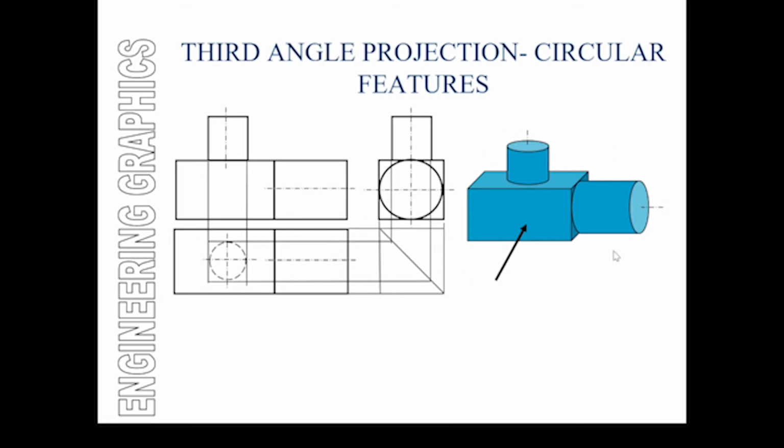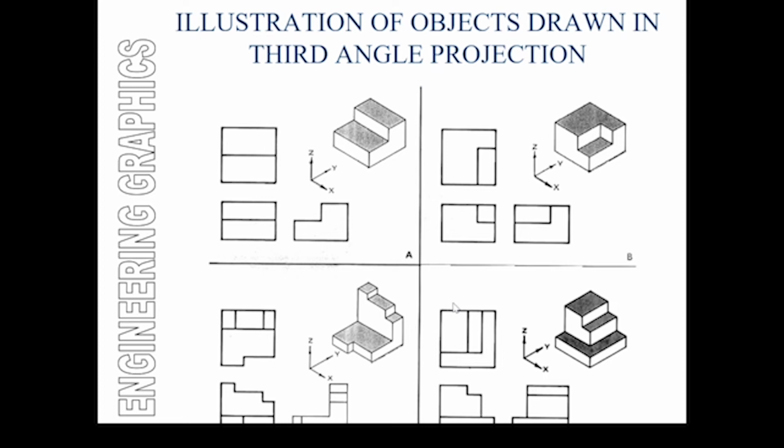You always have to imagine that you want to produce and provide information with probably only two views, and that should be enough for anybody to deduce the object they're looking at. And if you were to think about that and that view together, or maybe that and that view together, that's enough to know what this object is. Once you've seen it, it's difficult to unsee. However, if I hadn't seen that, I know there's a center line there, so that's a circular object. There's a center line there, that means it sits centrally, etc. So there's a lot of information that we can tally.